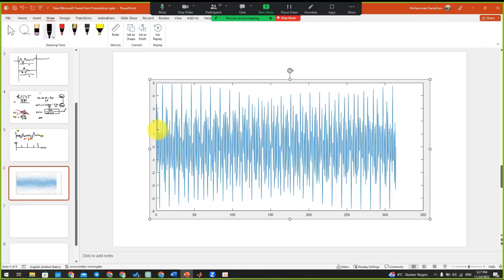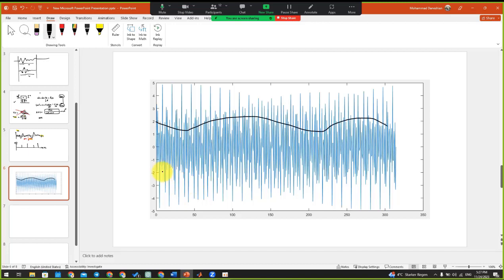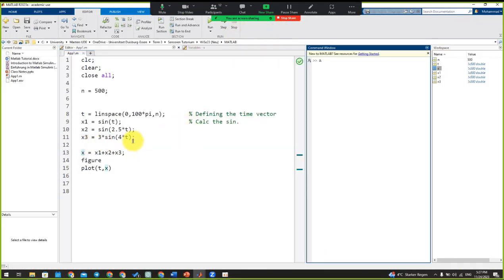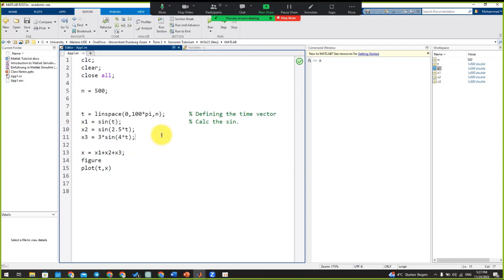So it is right, maybe you can see with your bare eye that here we do have a signal in this area, and here also with these peaks we do have a signal, and here as well we do have a signal. But the main thing is you cannot identify them anymore, especially if you don't define them by hand and you receive this information from a sensor. So what we want to do is actually an FFT and see what kind of different frequency components we have here.